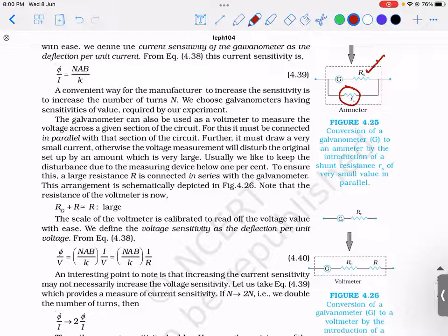Okay. Dependent on if this whole combination is called an ammeter, let's say that the ammeter is supposed to measure the value of current to be I. Now the current will get split as IG and I minus IG. I said IG because IG is the full scale deflection current, meaning the current that you need to pass so that the galvanometer's pointer is at the end division available in that galvanometer. So the rest is I minus IG.